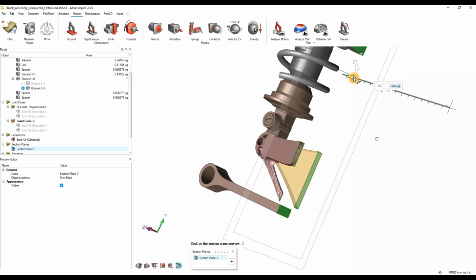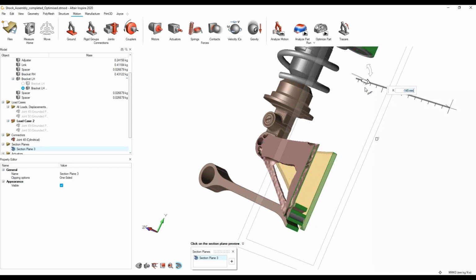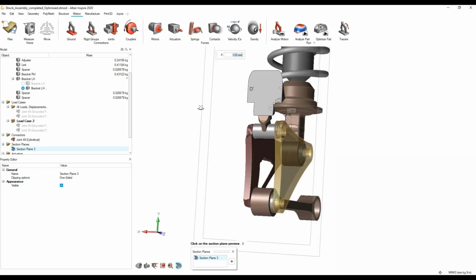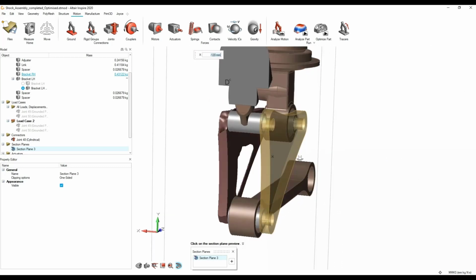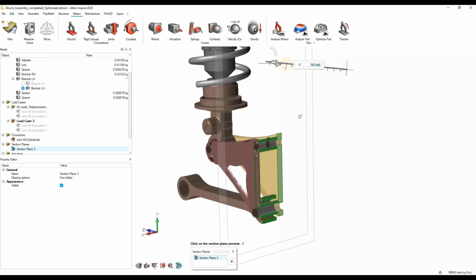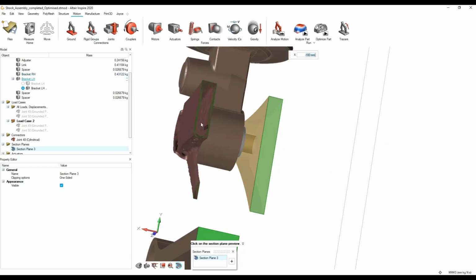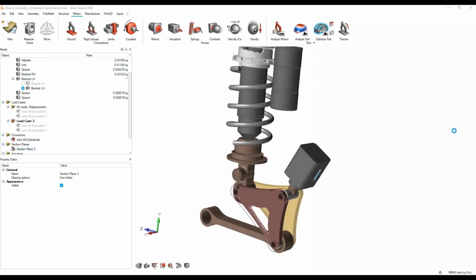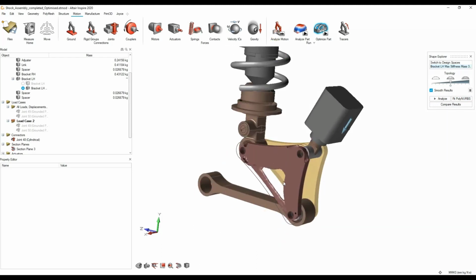You can make it with solid beams, it doesn't have to be hollow, it just needs to be lighter than what it previously was, and you can redesign your part. Previously it was a thick solid like this bracket here, and then it tells you to hollow some of the areas out as well. And from the optimization itself, you can very quickly fit PolyNURBS to it to then generate geometry out of it, or you can click to analyze exactly the stresses that go through this optimized part during the MBD run, to see if all of these elements are still within your stress targets as well.